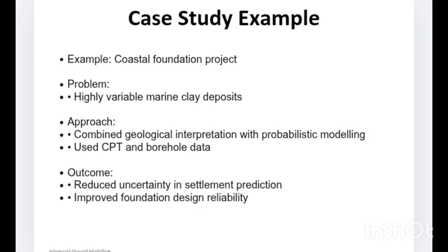Now, the traditional deterministic analysis produced inconsistent settlement predictions. As a result, we had to think of another investigation approach. So what was used? A combined approach was used, where borehole data, cone penetration test data, laboratory testing, geological interpretations, and a probabilistic model, all of these were combined.